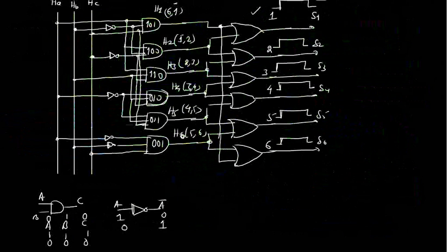Because the intention is what? The rotor back EMF is trapezoidal. So for the motor phase back EMF, you need to inject a square wave current. To inject a square wave current, you have to select the switches of the inverter which will ensure that the current is injected in synchronization with the flat top of the back EMF.